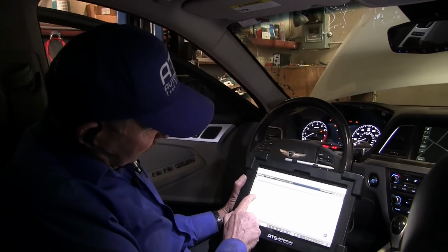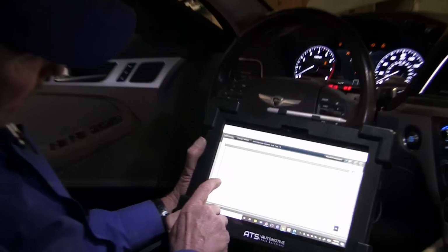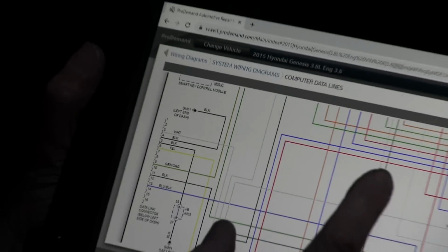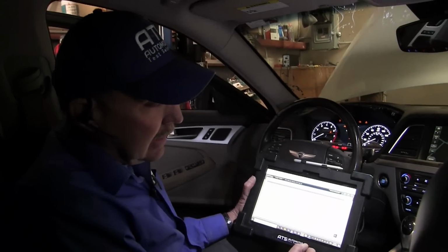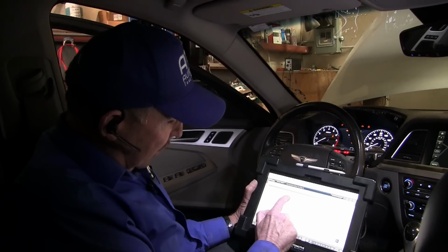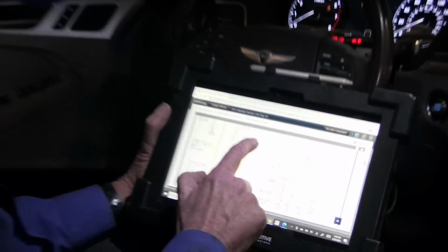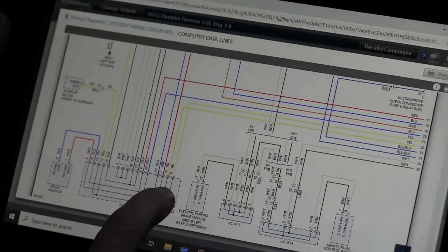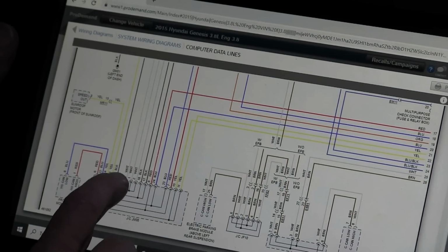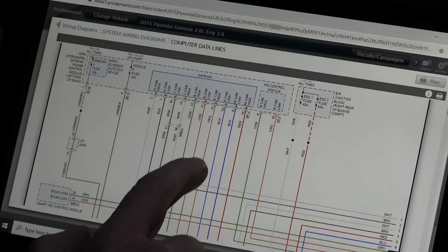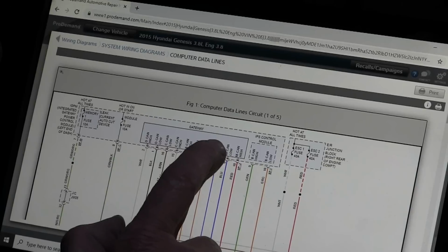But I can also see where I've got pin 3 and 11, and that's usually a medium speed bus, but on some of these Hyundai Kia systems, that can be a CAN high bus. So I want to go ahead and follow these wires down, and we can see this white one comes into the bridge, and we have a breakout right here, and we've got these two, the white and the black, and we're going to follow those up here, and they're going to go into a gateway.